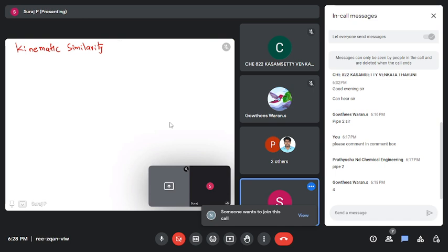What is the RPM of the motor? Those things we will find using a model. Then we will use similarities like geometric similarity, kinematic similarity and dynamic similarity for calculation of the prototype parameters.